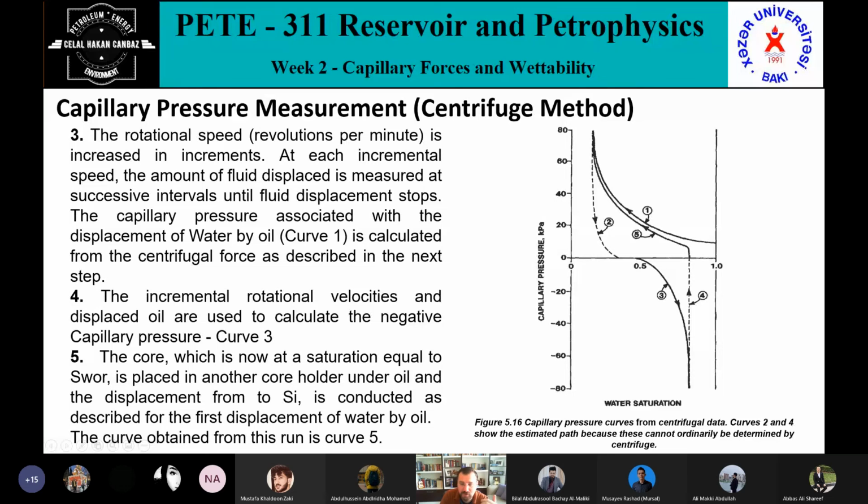Okay. So in the fourth part, the core containing oil and water at irreducible saturation is removed from the core holder and placed in another similar core holder, and is filled with water until the core is completely submerged in the brine. Okay. So I have two core samples. The first one I used already. The second one is a neighbor core, maybe it has been taken from the same interval. So I will use this same core for the second part of the